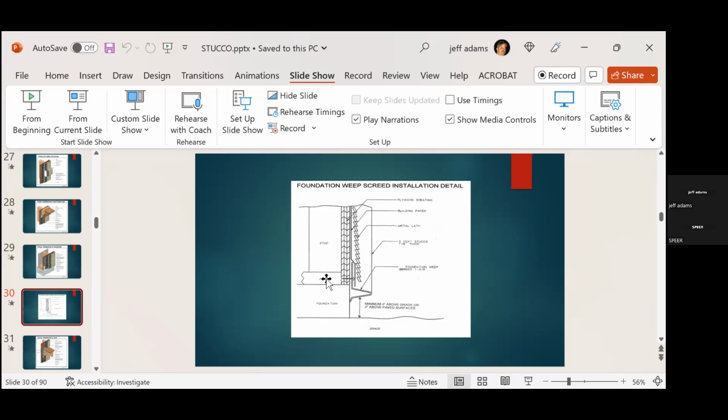The moisture is getting into this toe plate and it's soaking up into the studs. These studs are not pressure treated. If you notice, the code will tell you that if they're not pressure treated, they have to clear by at least 2 inches. This toe plate here is not, so it creates an issue on all those columns at your porches and stuff. They're just rotting away big time, creating a huge amount of issues.